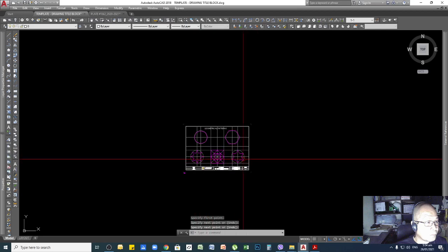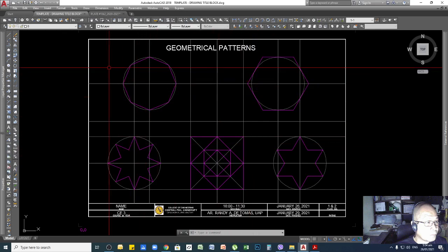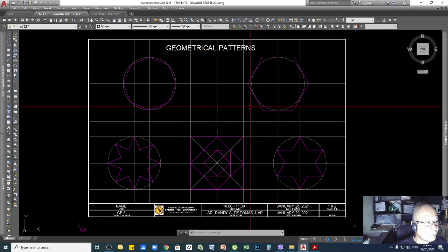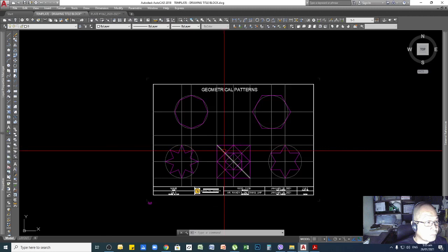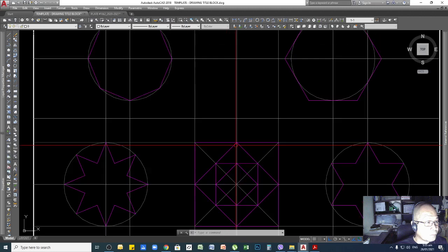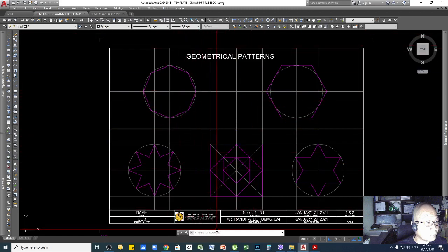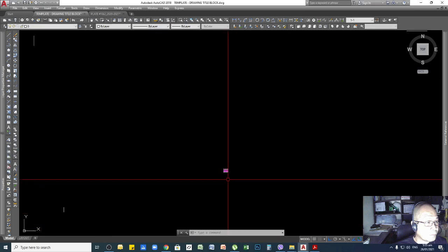Then without knowing, I'm working here, I don't know that somewhere outside this box has objects. Okay, and I'm concentrating only on this area by using or dragging my mouse in and out on this area. But once I'm done with my drawing, if I use the word zoom, enter, and then if I put that option extend, enter, see, my drawing becomes very small.